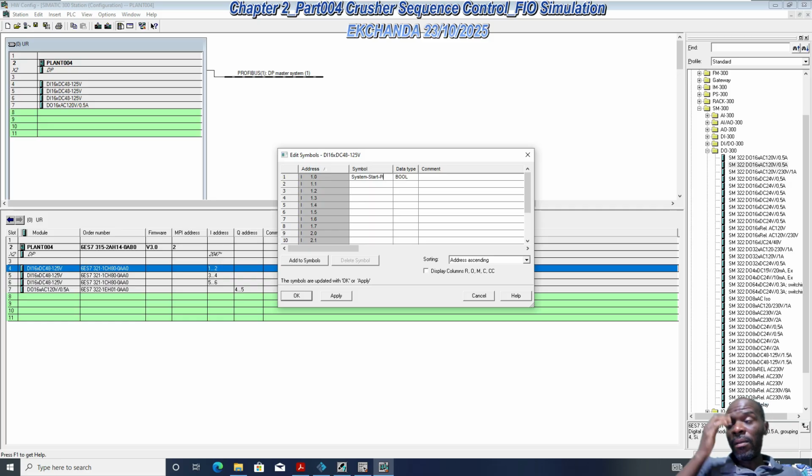So now the only thing I'm doing is, as opposed to having to create separate tags for the same thing, because these are essentially just going to reference the same control aspect. So system start, but now this is a physical input, external to the program. This is expected to be the one which gives its state to the memory bit address M10.0 for system start. I'm just adding PI just to remind us that it's system start, but associated to the physical input module.